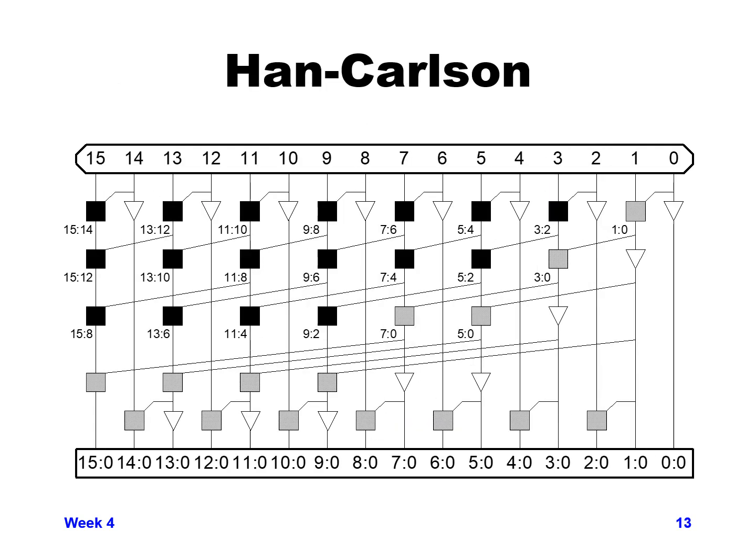So another adder tree taxonomy is the Han-Carlson design. So the previous 3 designs we were maxing out one of the 3 parameters that we were looking at, F, L, or T. This design is trying to balance between the logic levels and the wire tracks.